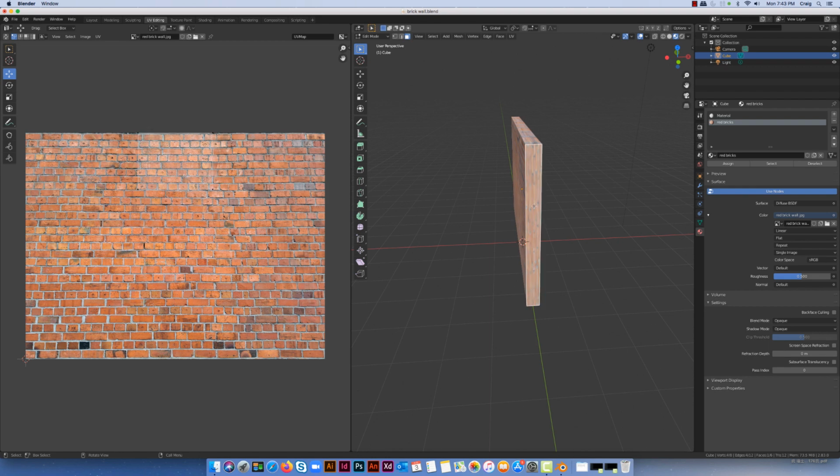So I'm going to select this face here, I'm going to unwrap, but this time instead of having a whole series of bricks across, the reality is when we look at a double brick wall, it's probably, and this isn't going to be perfect, only about the width of one brick, so I'm just going to use this one as the guide. It's not going to be perfect because they're not going to line up perfectly. We have some little cut off bricks here, and ideally if it was perfect there would be 2 bricks filling up that space.